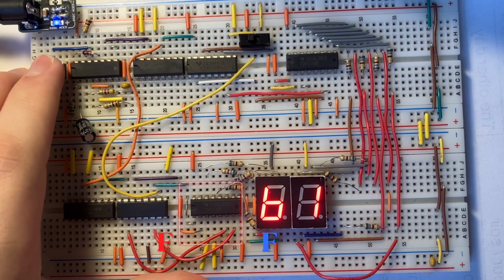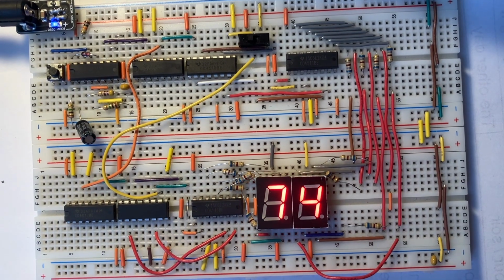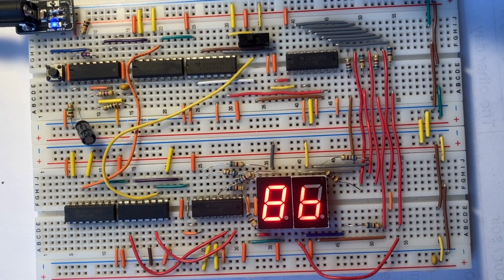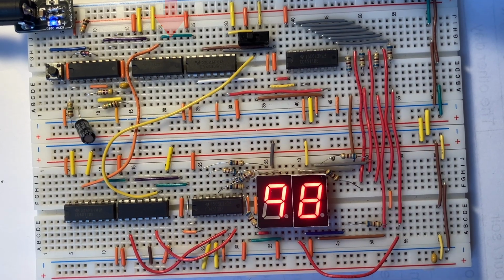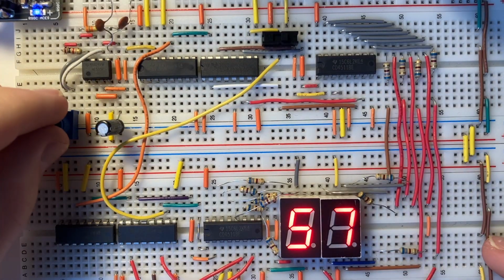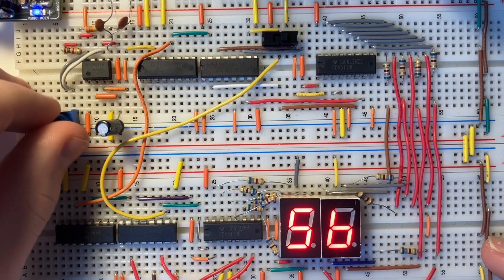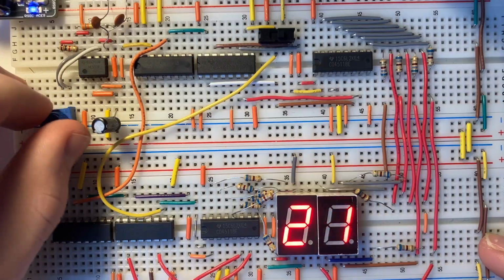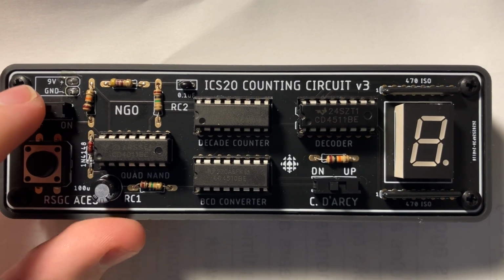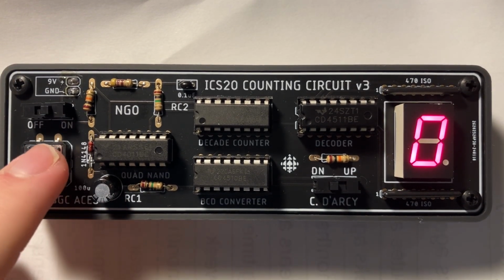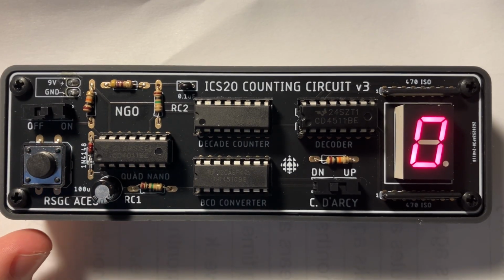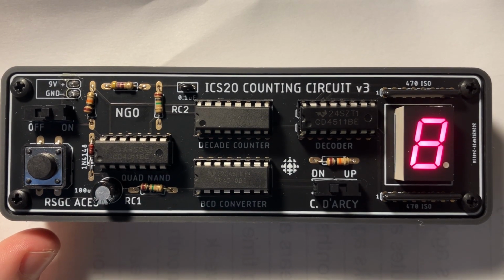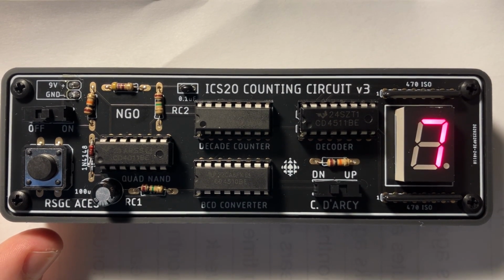To increase the count, sections D to G have to be repeated, with the 4017 of the single digit count being connected to the clock signal of the second 4017, providing the tens digit a 10 times slower oscillation than previously. I hope that by watching this video you fully understand the counting circuit and can develop your own prototype and PCB to ensure that you have your own counting circuit.